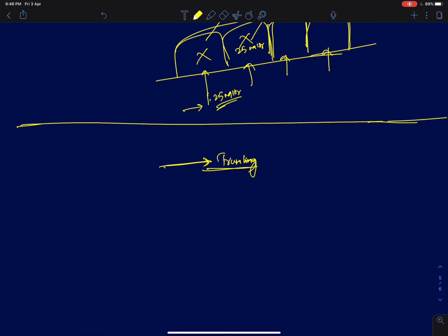So in any communication system or a cellular system, once we divide it into cells, each cell, I said we are going to give k channels per cell, which means previously I said if it's an FDMA system, simultaneously only k users can be supported. But then if you actually see, the number of users in a cell will normally be much greater than k.